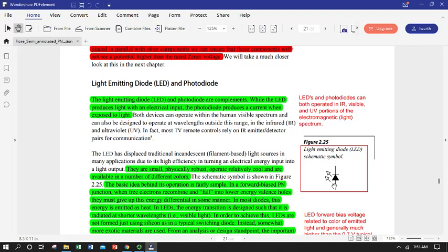Basically, one of the characteristics these have is that as charge carriers come across the interface, in addition to jumping the energy hill, some of the voltage that you supply does more than just push your charge carriers up or down the energy hill at your interface. Some of that applied voltage that you're putting across the diode is converted to light.